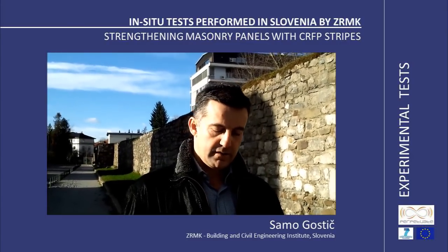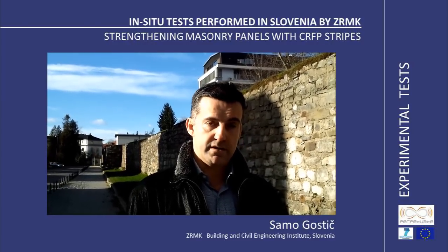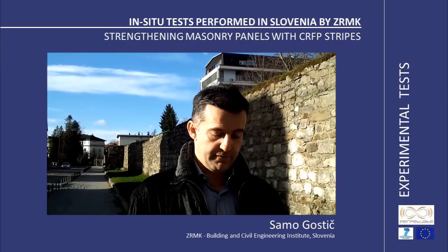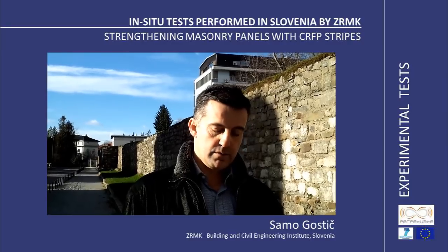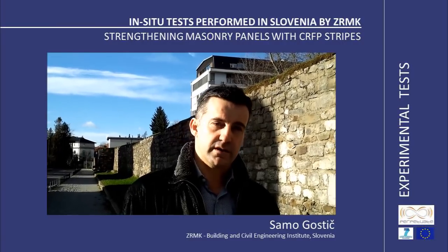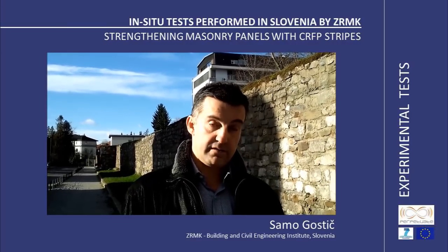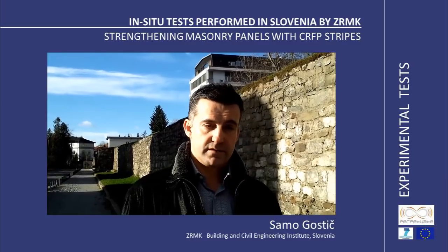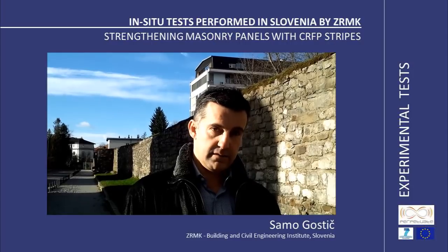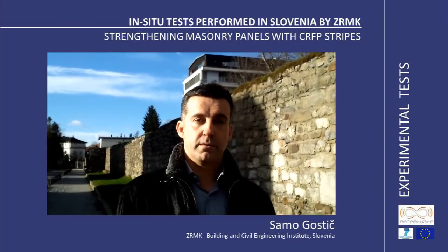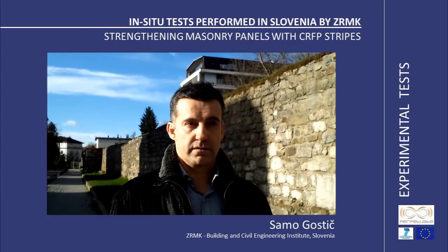Different tests that were not sufficiently investigated experimentally before, like walls common in Islamic architecture, the effects of tying the arches, and also strengthening of masonry walls with FRPs, were tested during the PERPETUATE project. Experiments were crucial to get the response to lateral loads of those different structures, and also to gather the performance points that are needed when analyzing cultural heritage buildings by the PERPETUATE procedure to get the resistance to earthquake loading.